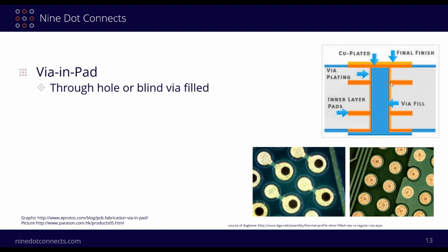So if you had a through hole over here, they're going to go through the process of capping down the bottom. They're going to fill this with a material. It could be either conductive or non-conductive, because remember, your hole has already been plated at this point in time. And so the idea over here is to put a material in here that's not going to outgas, and it's going to be able to support this copper plating that's done on the top here when heat is being applied to it. Nor do you want it to round out or bubble in there. So that's what they're doing here, filling out the material here to support this, and they're going to plate that over.